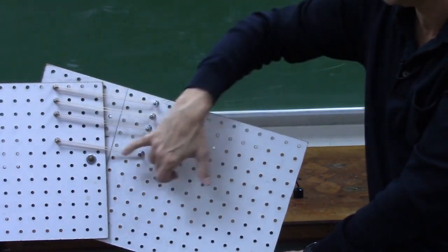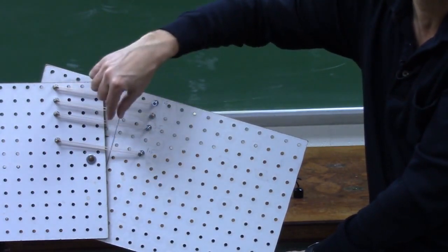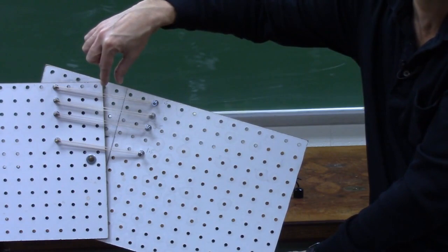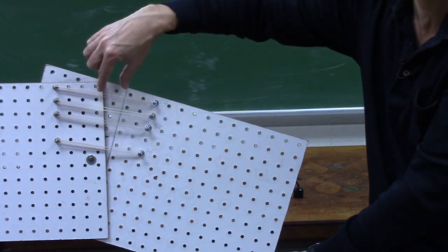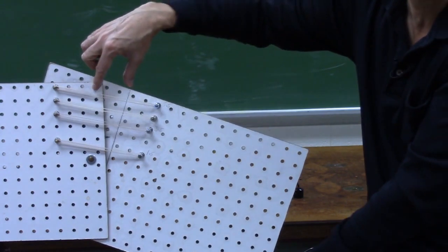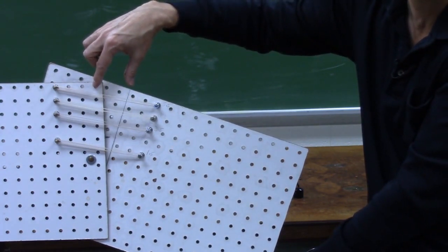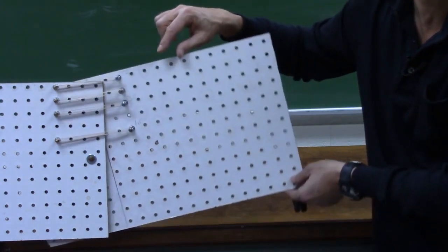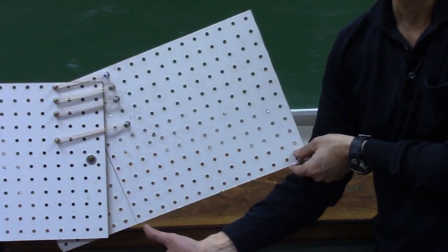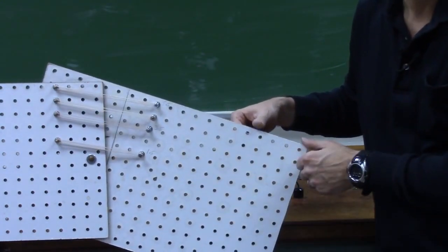And then what the pencil mark makes intuitive here is that the strain of these fibers of the beam, a distance y above the neutral surface, is proportional to y. So the farther up you are from the neutral surface, the larger the strain, and in a proportional way, since this is just a triangle. So the strain is proportional to how far you are above the neutral surface for a beam that is frowning, and if the beam were smiling, it would be the other way around. The bottom, the strain would be proportional to how far we are below the neutral surface, and the top would be in compression. But we've built this model so that it frowns rather than smiling.